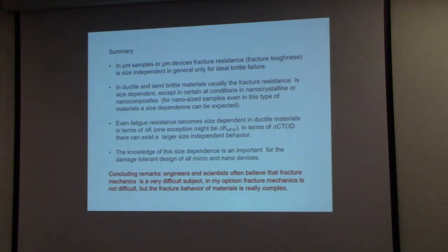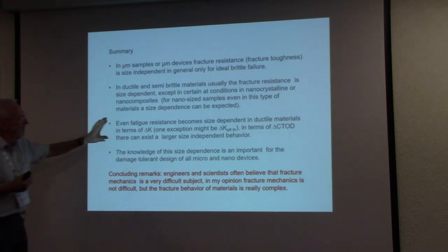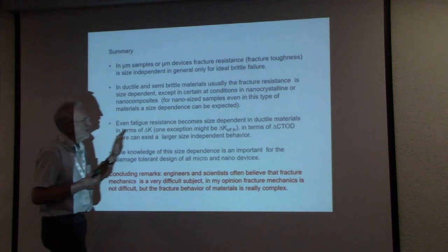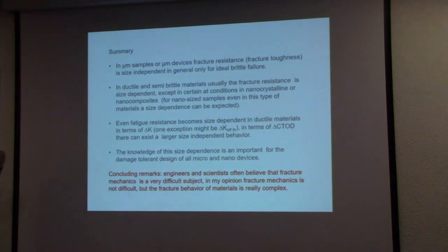Maybe we have some problems with the estimation of the plasticity to determine the cyclic crack tip opening displacement, but fracture mechanics at a low crack growth rate should be applicable in the case of fatigue, with some problems.